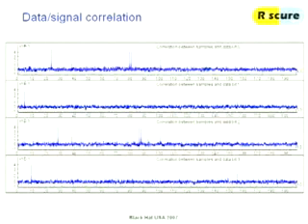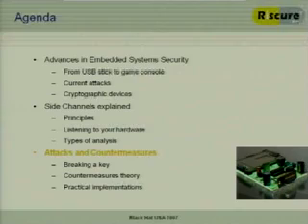There's no point in being able to randomize the key. So you can't use this directly to find the key. For the input, you can use it directly. You can directly correlate your input with the measurements and find where it's used in the program. For the key, you have to figure out something else. And that's the differential power attack that I'll show after this.